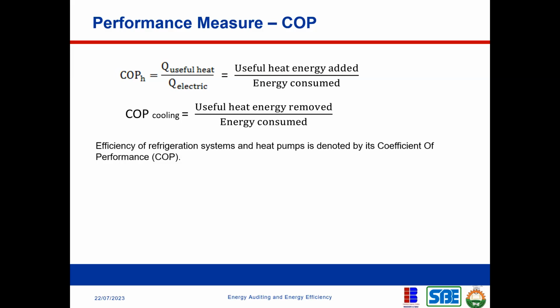And then there is now a concept for it. We call it coefficient of performance, and that's what we call COP. You can check the coefficient of performance of a heat pump, and you'll be seeing something like 4, meaning that for every unit of energy it consumes, it produces 4 units of energy output. Just 1 unit that you put in, you have 4 outputs. That's what it means, and that's what we refer to as coefficient of performance.